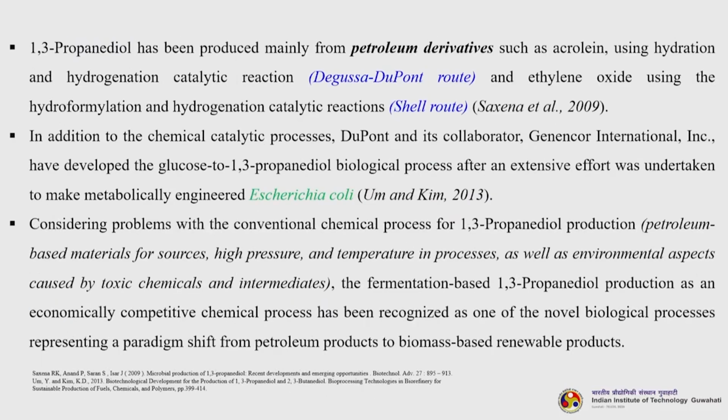1,3 propanediol has been produced mainly from petroleum derivatives such as acrolein using hydration and hydrogenation catalytic reactions, the well known Degussa-DuPont route, and from ethylene oxide using hydroformylation and hydrogenation catalytic reactions, the well known Shell route.